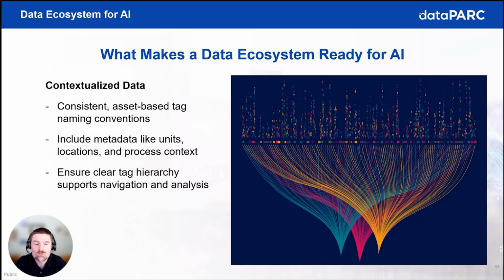If you can create an organized asset hierarchy, and then tie your data tags to those assets, and then also utilize a consistent and logical tag naming and tag description scheme throughout your database, it's going to make, obviously for humans, but also for AI programs, accessing that data and sorting through it for the purposes of analysis and calculations much, much easier.